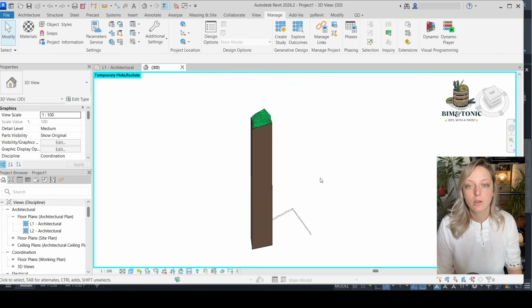The reason why the soil is this high is because we still haven't set up our survey points, our project base points, nor everything else about this site. Basically, the survey point is by default 0, and our terrain is at around 300-400 meters high, so it is essentially reaching from these base points of 0 to somewhere around 300 meters height, and that is why it's this high.